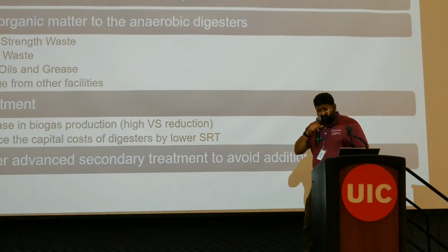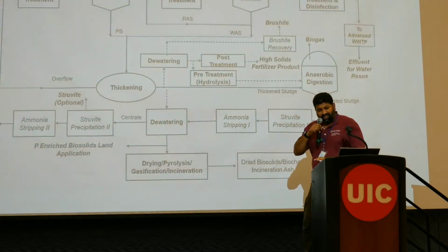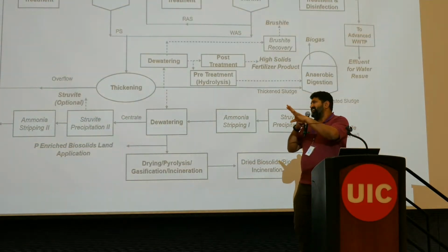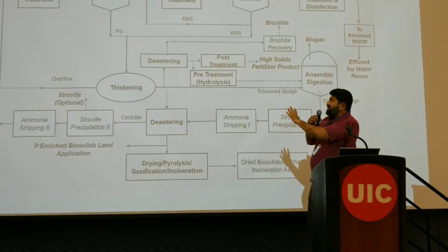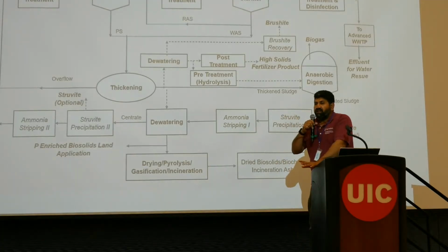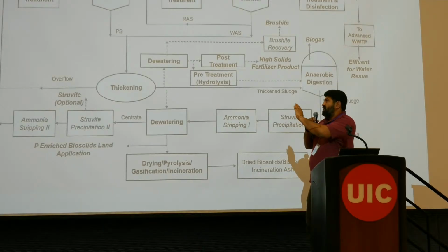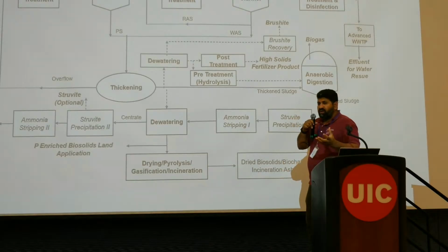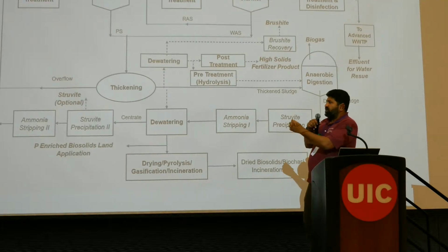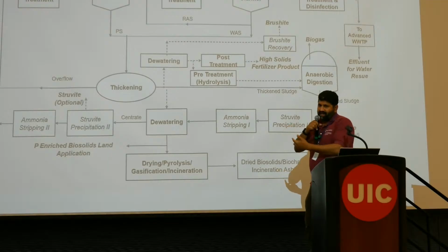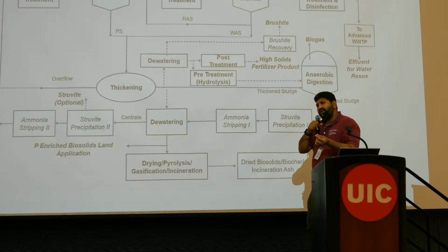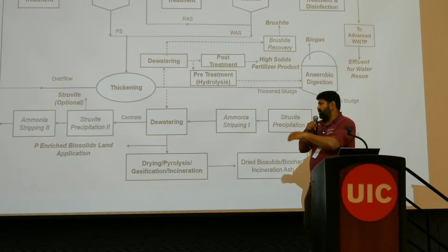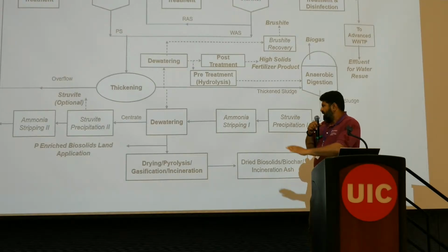And going maybe further beyond, we can think of opportunities for nutrient recovery from wastewater treatment plants. In every flow scheme, there is an opportunity to recover the soluble ammonia or the phosphorus from your streams, for use as a soil enhancement conditioner or even as pellets, which can be used as a fertilizer.